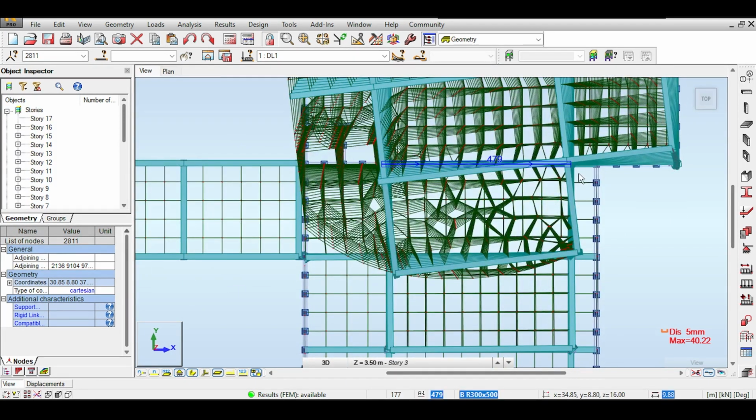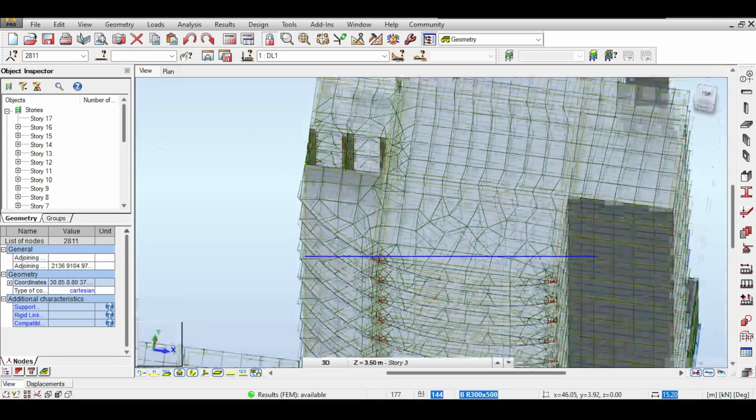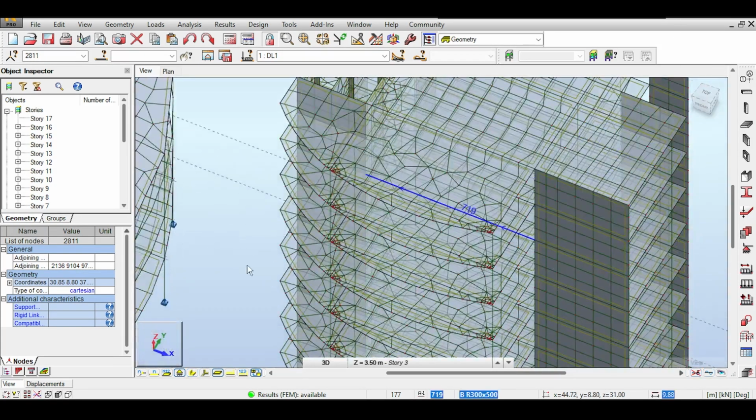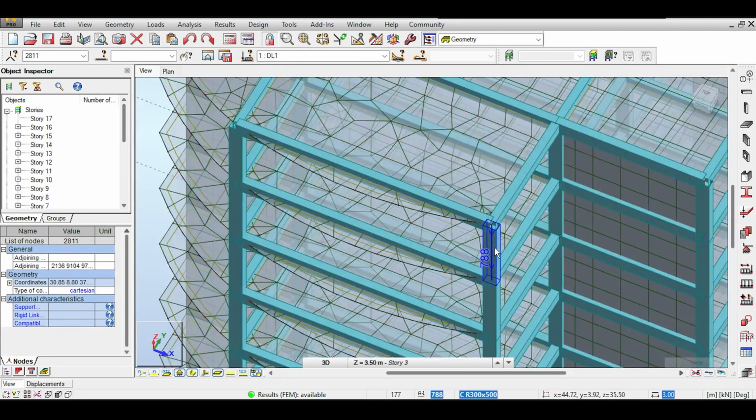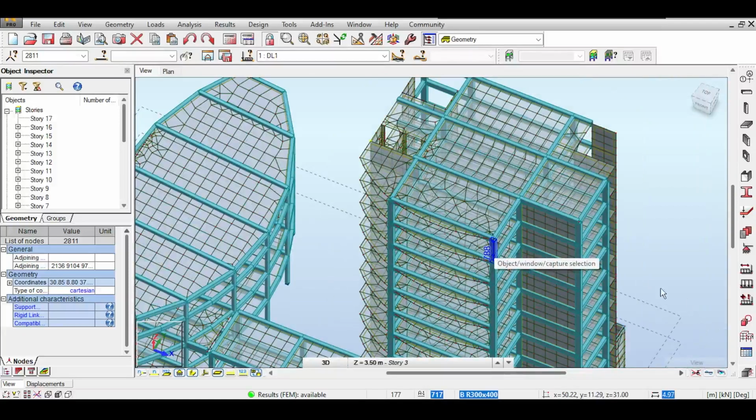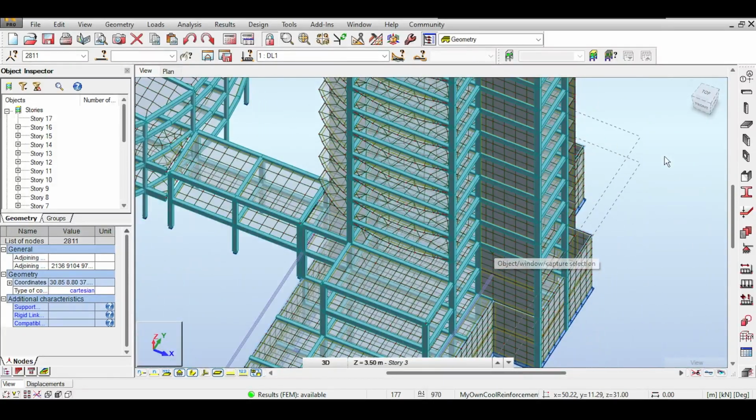That's stiffer. Also, something else I noticed is that I put columns which are really meek and weak. Like the columns are 300 by 500. Who does that? 300 by 500 for a multi-story? That's really weak. So what I will be doing now, well, that's gonna be a big nightmare. I need to increase the stiffness of the columns first.